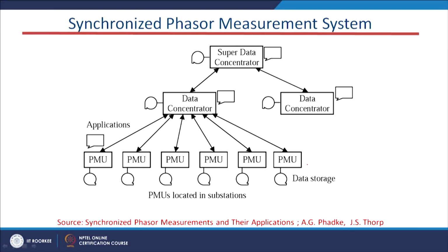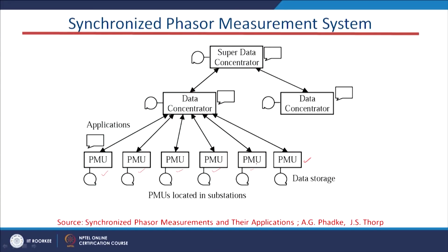First, at different buses of the power network, the PMUs are mostly placed optimally to save cost. We cannot place PMUs wherever we like, because at every bus we cannot put one PMU; we have to put them optimally. After placing the PMUs at the critical points, we will have complete observability of the system, or complete control of the voltage, current and frequency signals, where we can measure the voltage and current properly.